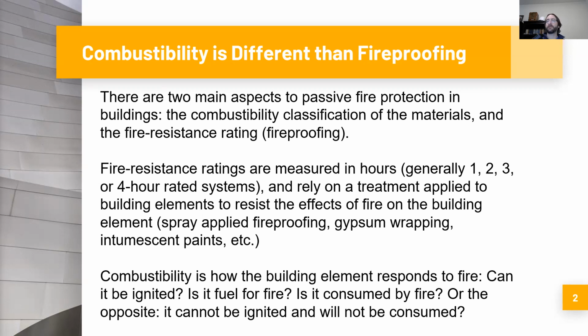So of course, when you're thinking about wood, yes, if you hold a flame to wood, it'll ignite and self-sustain the fire and burn and ultimately be consumed. Whereas a piece of steel, let's say you have a steel beam or a steel stud, you can hold a flame to it, and while the flame will of course heat up the element and it'll get hot, it won't ignite, meaning once you pull the flame away from the steel element, the fire is gone. It doesn't sustain a fire by itself.